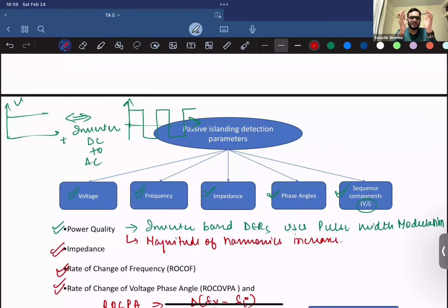What happened was you had transformers, right? Transformers are huge devices. I mean, they cover a lot of space, and what they do is they step up the voltage, right? But a converter can do the same thing by modulating the switches in such a way that it can convert AC to AC as well and AC to DC as well, right? But they take only a small part of your space. They are switches, I mean, they are non-linear loads, but what they are doing is they are removing the constraint of your space. And one more thing, how will you convert AC to DC or DC to AC? What are the different ways?